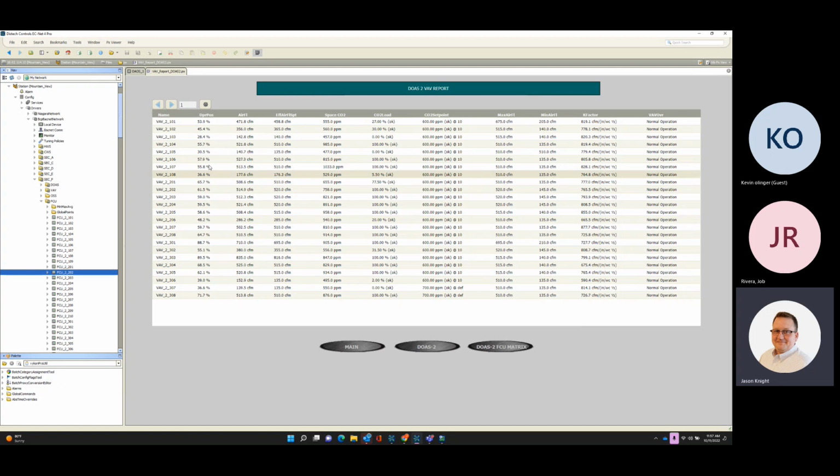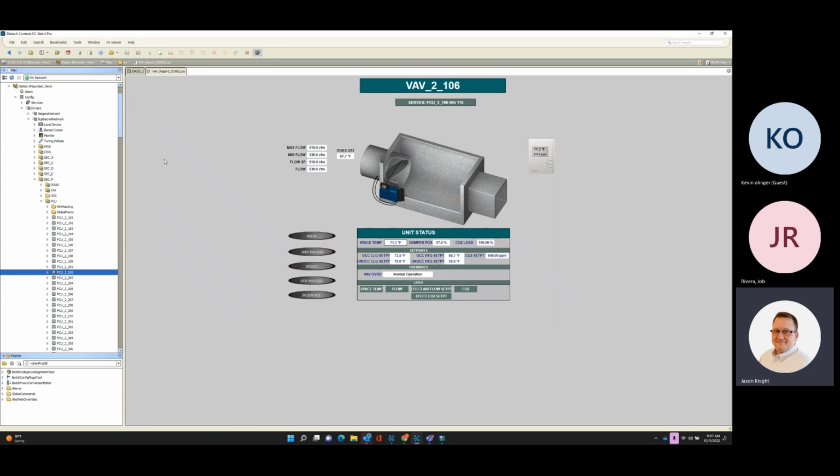With that being said, here's obviously the data table. I do have a hyperlink that you can link from this HTML5 table to that VAV box. That VAV box that serves that fan coil, you can see that the flow set point is 510. It's making 530 CFM. If we sat here and watched it, we would watch this just kind of dial back down based on the static pressure that the DOAS unit is making right now. So every couple minutes, this is going to readjust. It may go 57.6 because we're within 20 CFM, which is pretty tight.